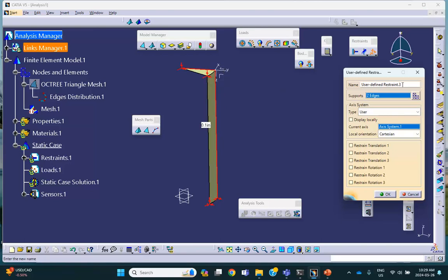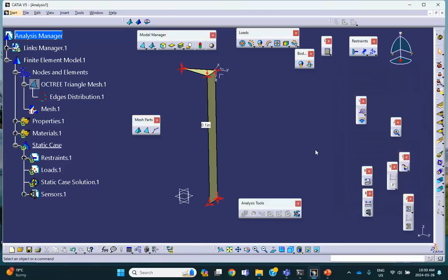So I'm going to rename this thing to be YZ symmetry. Axis System 1, I think that's called Axis System 1. Yeah, notice it's selected here. Okay, now do that. As soon as you say YZ, no displacement in X, and rotations opposite. And then we say okay.